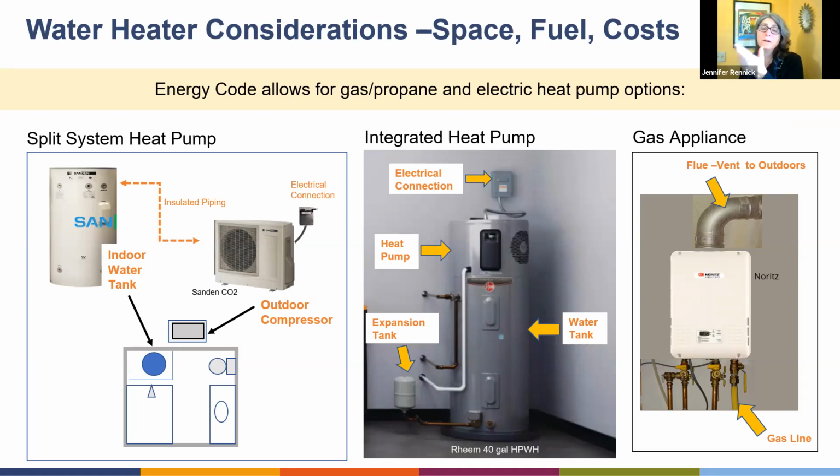If you're going to put in a garage like this, the clearances around this unit, just like you see it, are perfect, because they can exhaust the air straight away without hitting a wall or any other obstructions. That's the shorthand answer. And then I recommend you go watch a couple of those videos where we've got some good diagrams and talk about some of the clearances on the 3C Rent website.